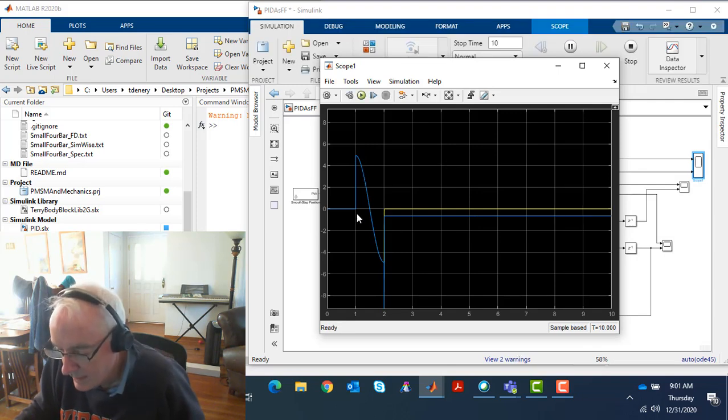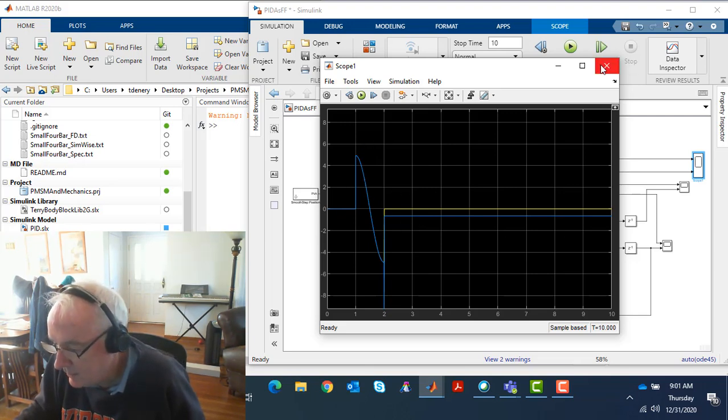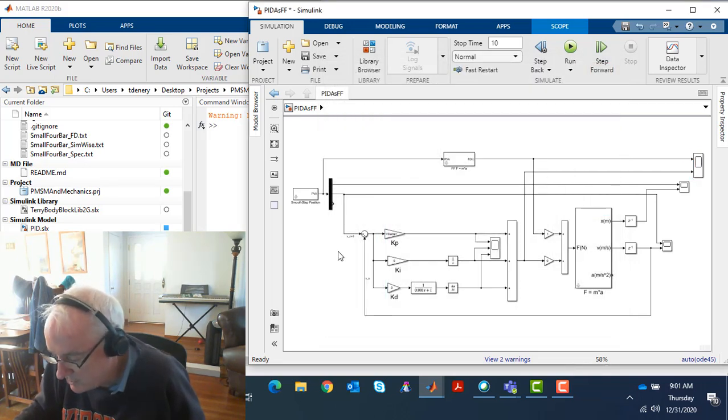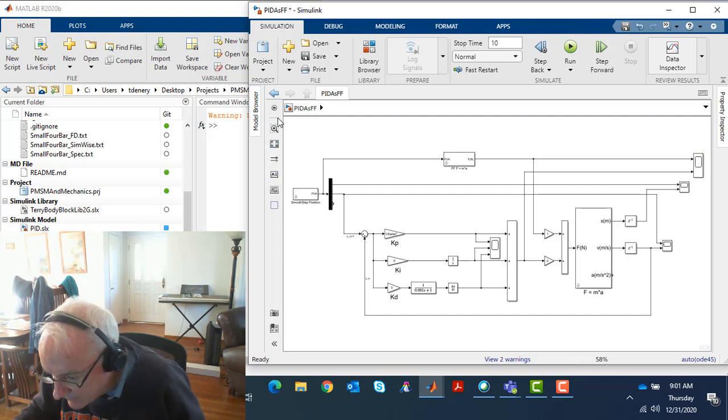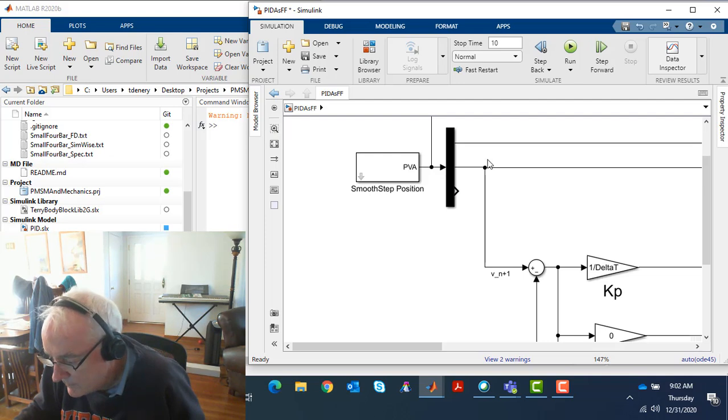Okay. And clearly, for most of the simulation, it's beautifully on top of what the feed forward calculation is. All right, and I want to give a little bit of explanation of how that happened. One thing you'll notice is that I'm actually doing velocity control, as I'm commanding based on the second signal. So the order is position, velocity, and then acceleration. I'm not even pulling it out. Okay, but I'm operating on velocity.